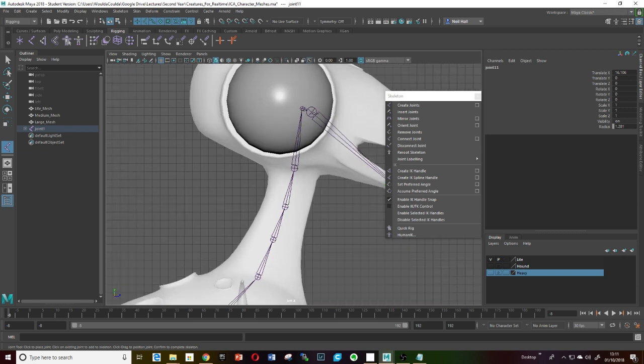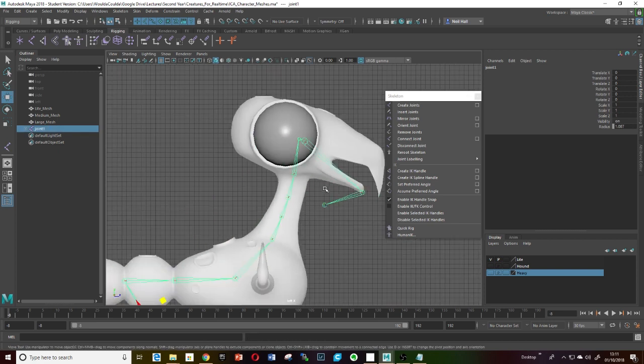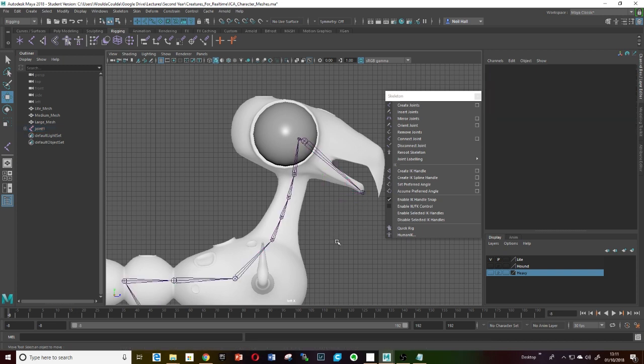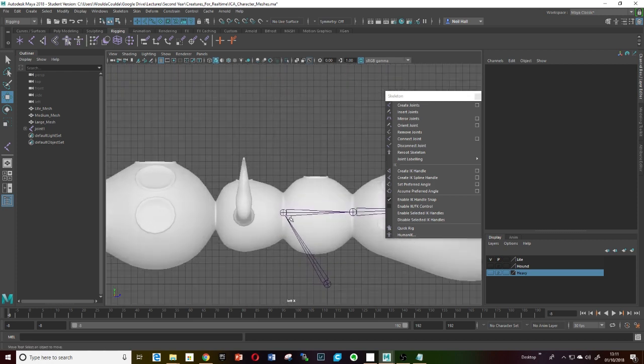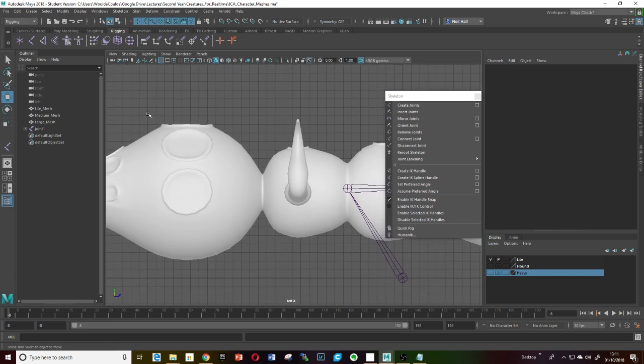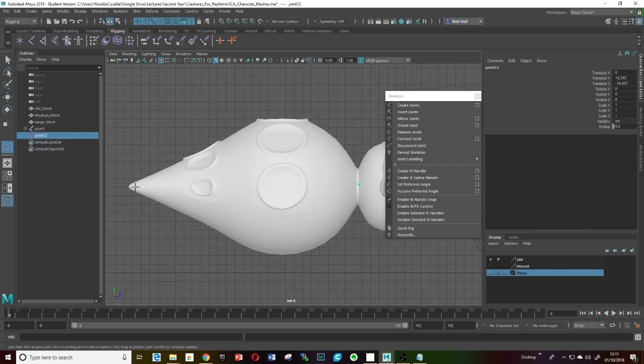But you might think, what's the point in this little thing here? If we right click, it draws the last bone. If you forget to do that, you can just click on it, hit delete, and it'll delete that bone. So you might think everything is in the right place. Now we can continue off and perhaps do the tail. So if you just select bones again, do this, and rather than left clicking, right click to finish it off, and there's our tail.